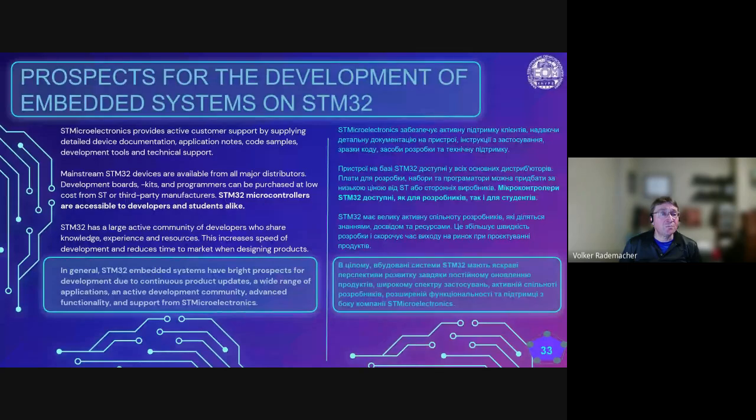There's another item up for the first point, device documentation, application notes. Also, don't forget about errata sheets. Many microcontrollers or many more complicated logic electronic devices have issues in the silicon. It is just something that happens. Pretty much all devices have errata sheets somewhere, where the device steppings are being discussed, what faults are available.